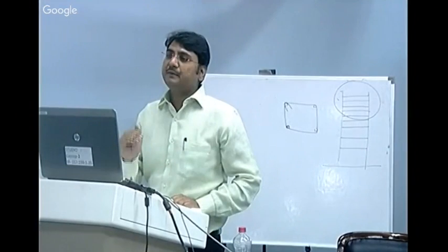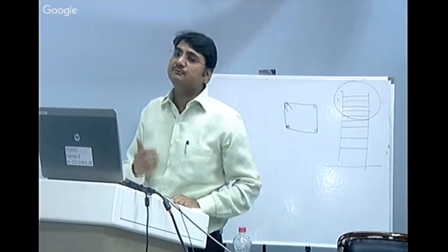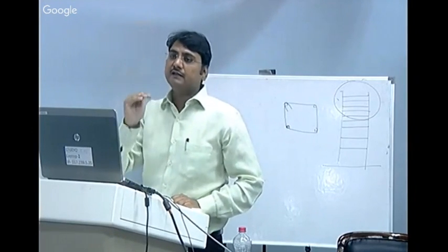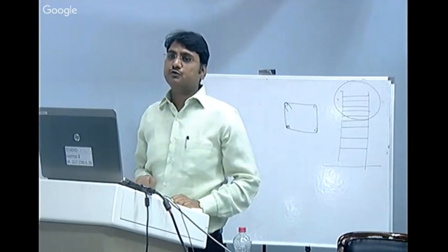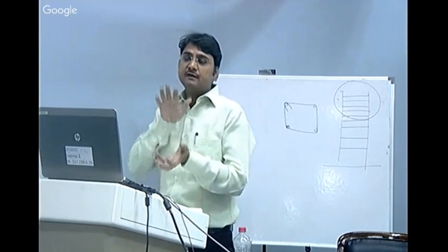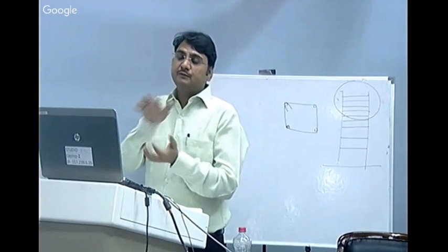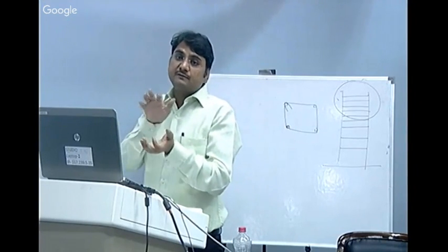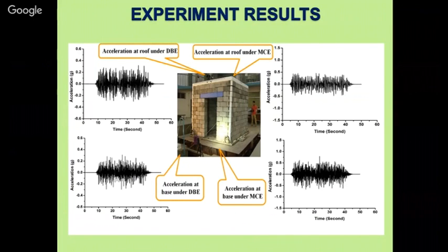As we go up and up, the performance of the building will improve drastically, because we are providing weight to the building, and these viscoelastic links will behave very well, because we have designed these links to behave under shear as well as bending. So when the forces come in, these viscoelastic links behave in shear as well as bending, and they will behave very well.